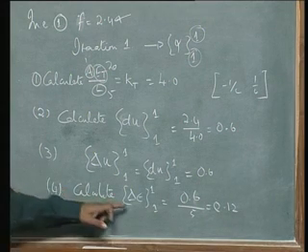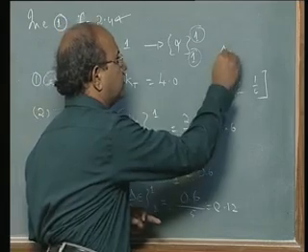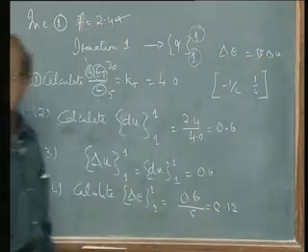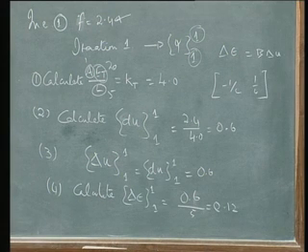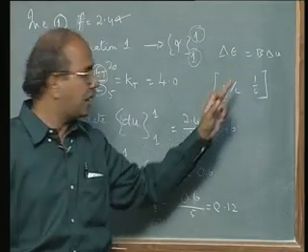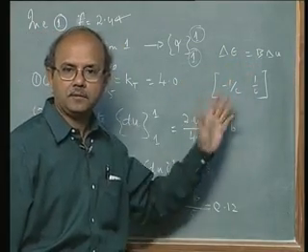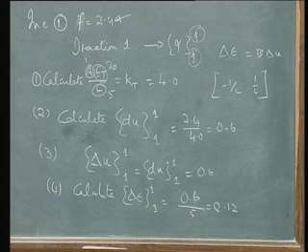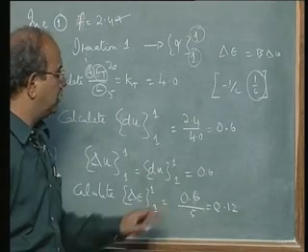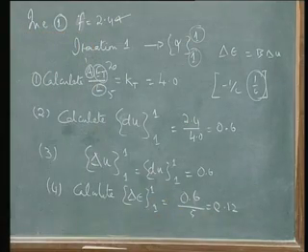So here I obtained delta epsilon, which is B delta U, with appropriate R and N. Now this B is the strain displacement relationship, minus 1 by L, 1 by L. The first one is for U1, U1 is equal to 0, so U2 is determined from that quantity, and hence I have 0.6 divided by 5, 0.12. So that's the next step.